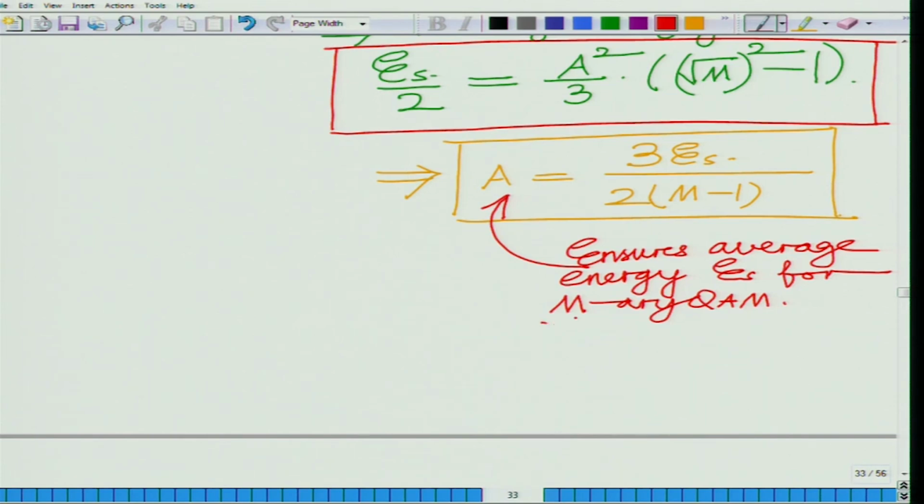Okay. So, all right. So, what we have done here is basically we have introduced a different modulation which is a generalized version of PAM. In fact, for that matter, a generalization of several schemes: PAM is a generalization of BPSK, and QAM basically is a generalization of all such modulation schemes. So, it contains a combination of two PAMs. There are two constituent pulse amplitude modulation constellations, each containing square root of M symbols. Therefore, the QAM is M-ary.